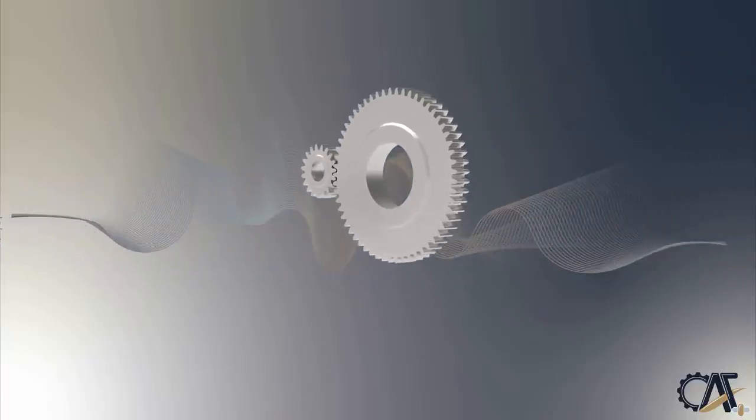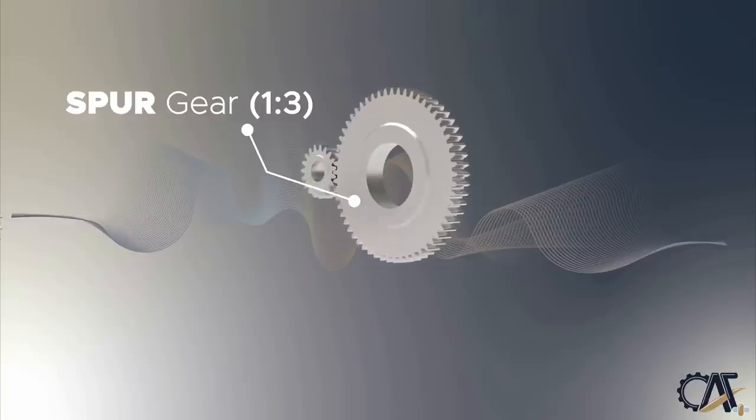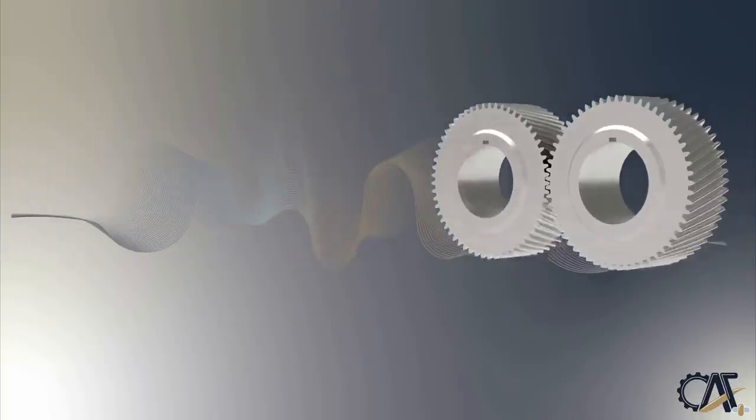Spur gears are usually used for low and medium speed applications, which are usually up to 3,600 revolutions per minute. They are not very often used in high speed applications. This is due to the loud noise they produce at high speeds. The benefits of spur gears are a simple design, cheap production, and maintenance.